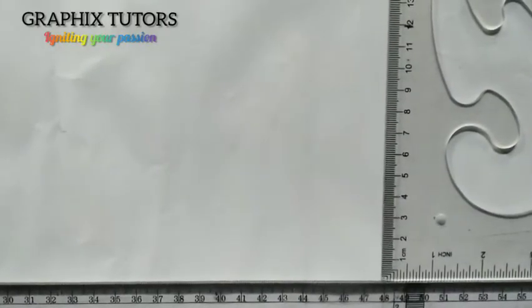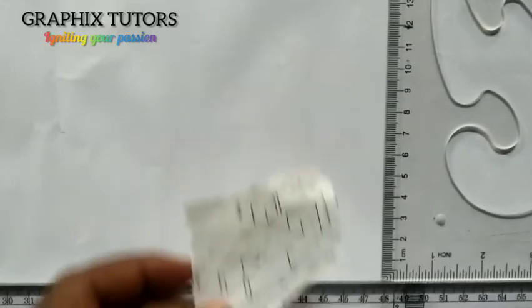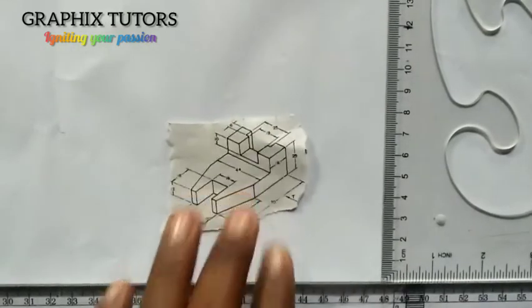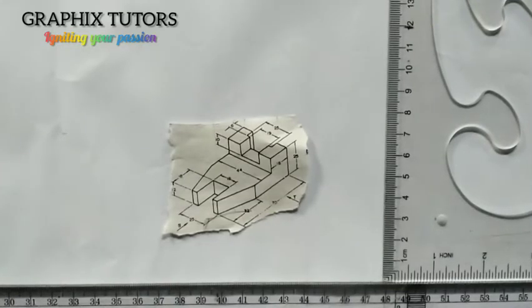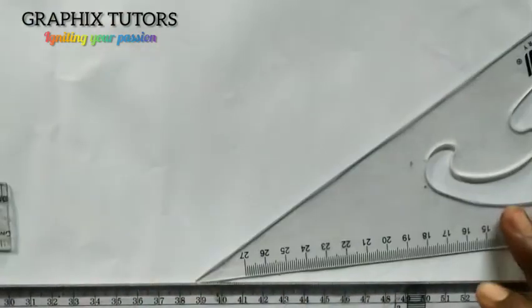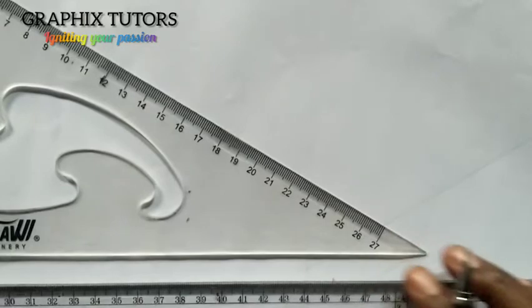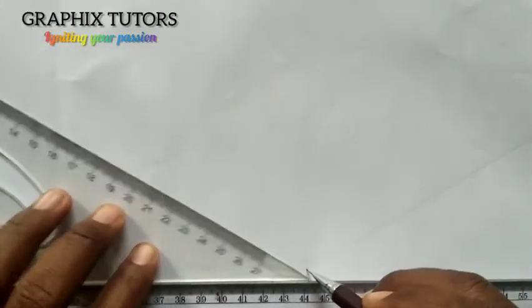Today we want to draw another figure in isometric, which is this figure. Now the first thing, when you hear the word isometric, what you should draw is your two axes inclined at what angle? 30 degrees, and this is what I did. I'm going to draw this, and I'll take it to this point. I'll draw this too. So these are the two axes you draw inclined that way, 30 degrees.